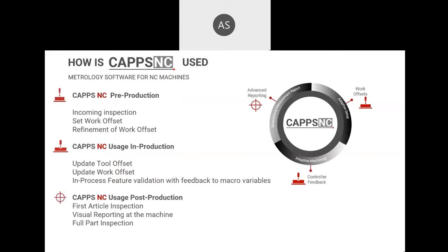Well, it could say, okay, I'm going to set macro variable pound 53, for example, to a 1. And then when it jumps back into the cutting cycle, it would read pound 53 and say, oh, it's equal to 1. That means I got a problem. I should stop, or I should do whatever I'm going to do based on that macro variable being set to 1.